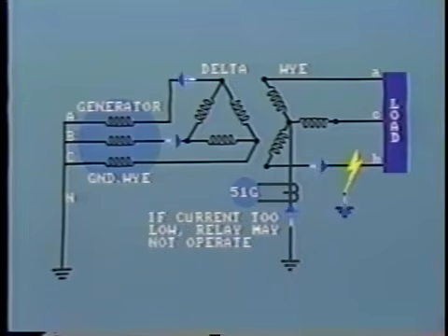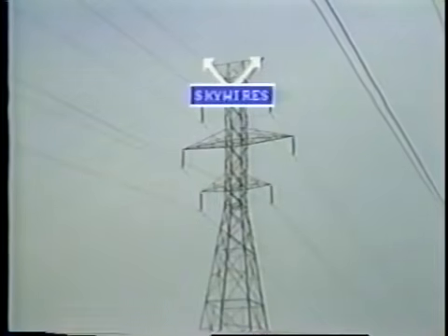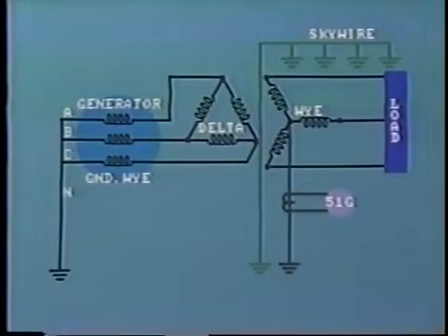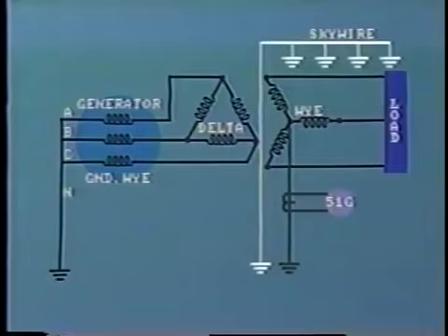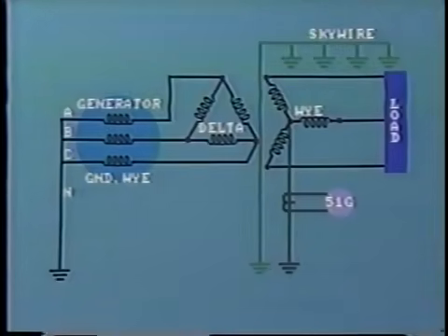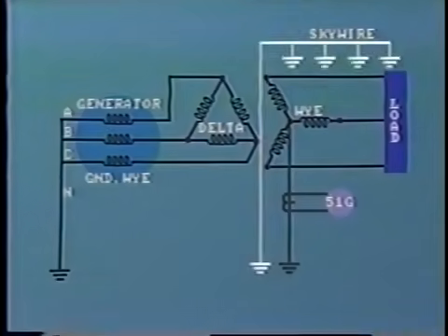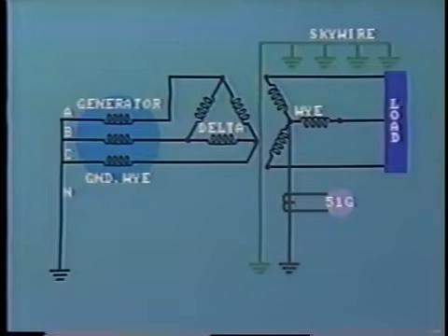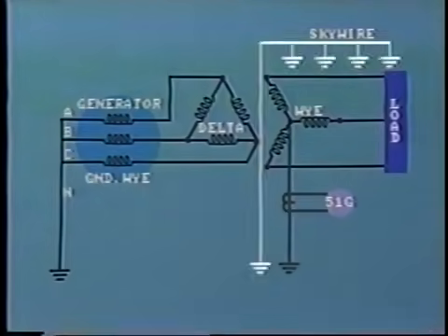But often another path is provided. For example, with high voltage transmission lines, the steel towers are connected together at the top by a bare ground wire or sky wire. This ground wire goes right back to the substation structure, which is, of course, grounded to the mat. Consequently, the ground wire provides a parallel path to current flow through the earth.